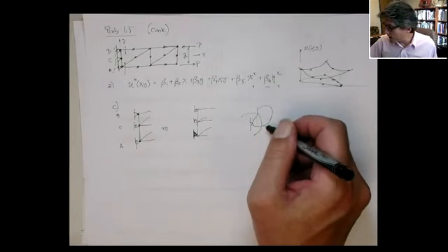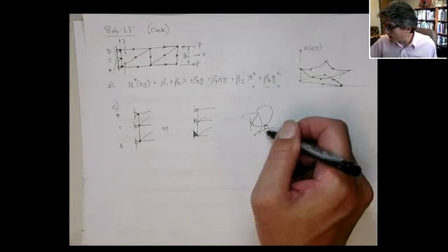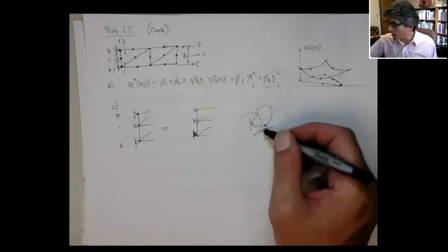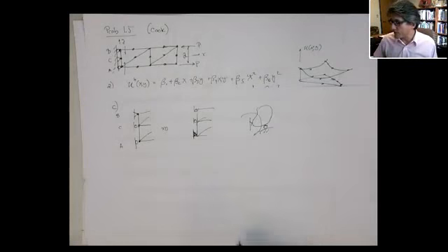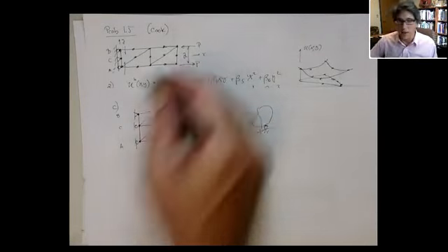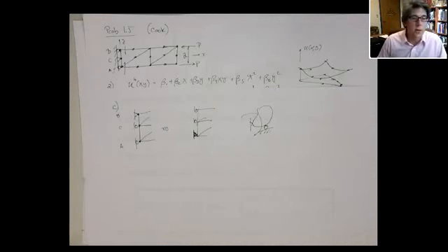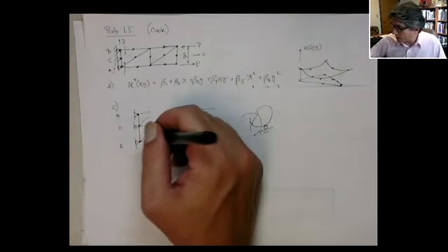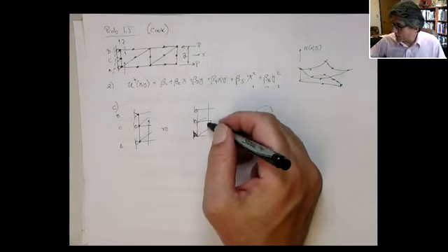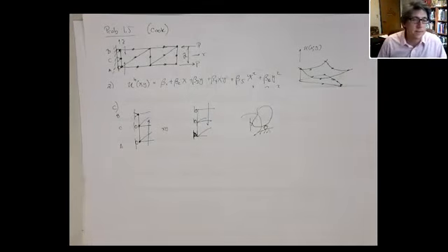So then usually if you pin something and put a roller at one point, that will kinematically constrain it. Now, where you put the roller and the pin point will have an effect on the stress distribution. In this particular case, these are equivalent to this, and you'll get the same thing. Both of them, this one will be fixed here and allow these things to freely move up. This one will allow these to freely move down, okay? And so you won't have any force constraining those.